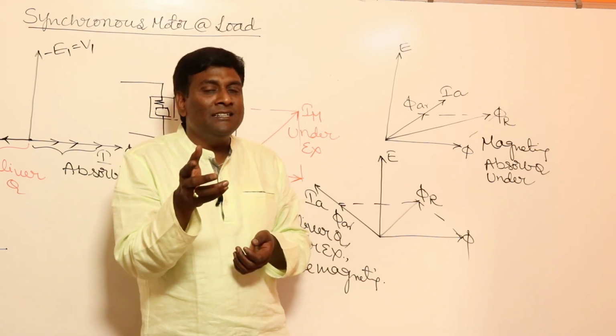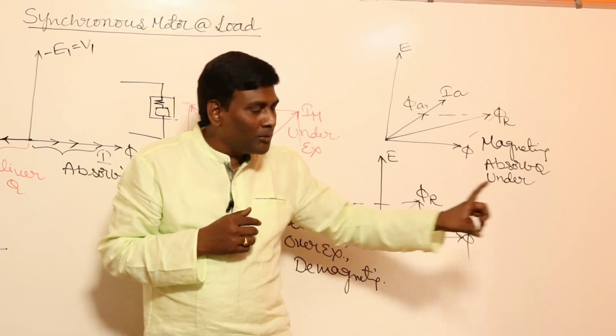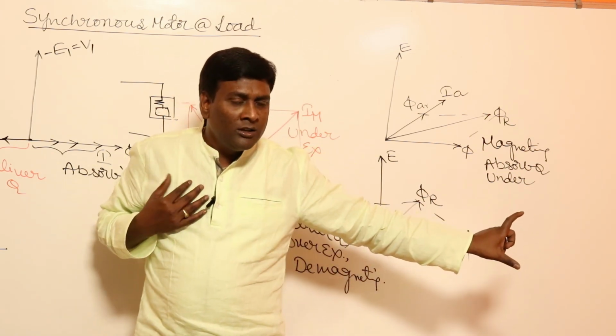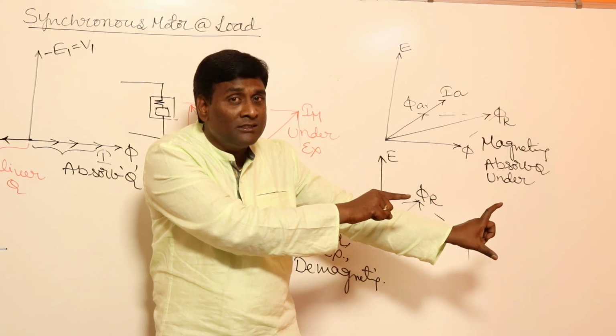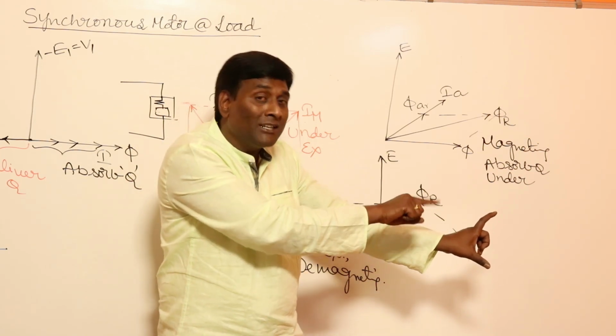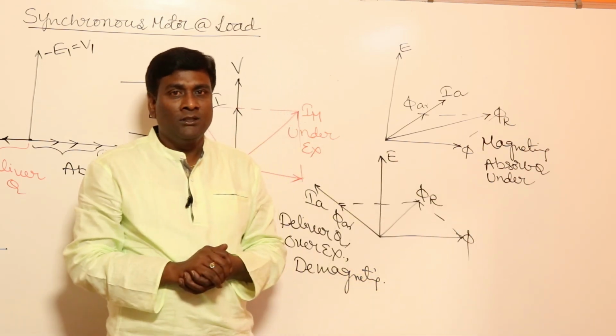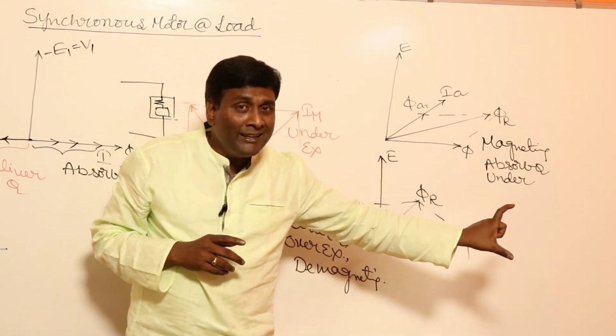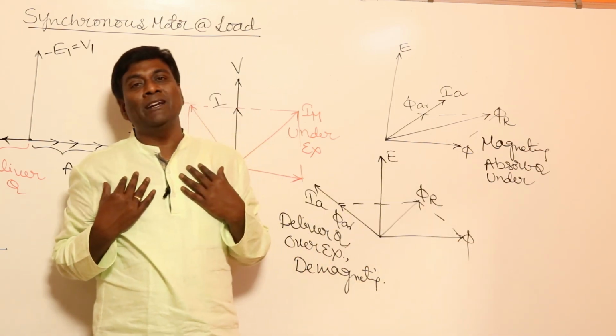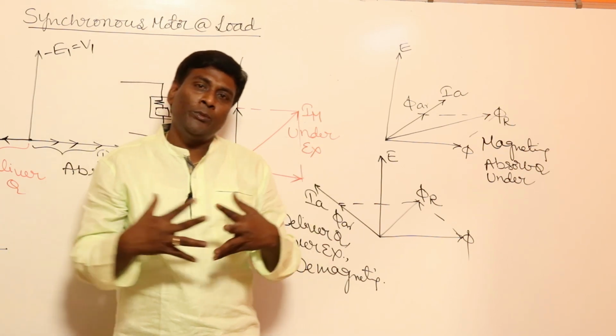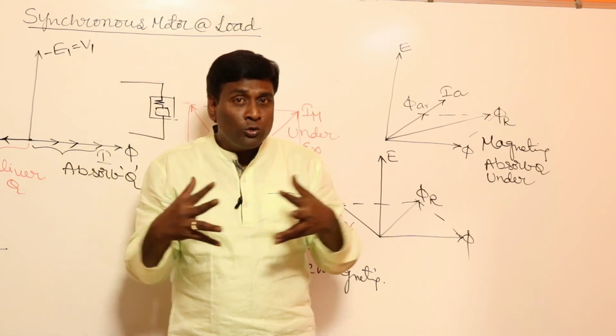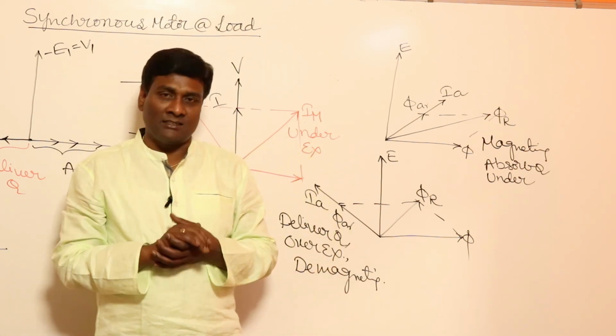As a motor, when it delivers, an overexcited synchronous machine delivers reactive power. Let us think of the motor: I'm the alternator, that is the motor. When the motor delivers, it should have capacitive effects. What is the power factor of the motor? Leading. So my motor operating at leading delivers, generator operating at lagging delivers, both should be overexcited. So both should have demagnetizing armature reaction effects.